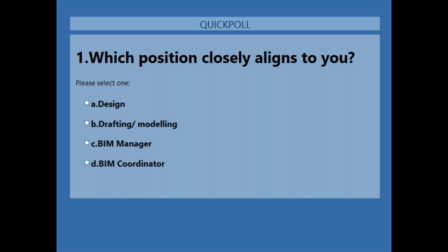Could you please repeat base point and survey point? Okay, I'm sorry, I was not following the chat while I was presenting. Base points and survey points are something that every project has. If you're using any files as a reference in your main project file, you can review or expose the linked file's base point and survey point.